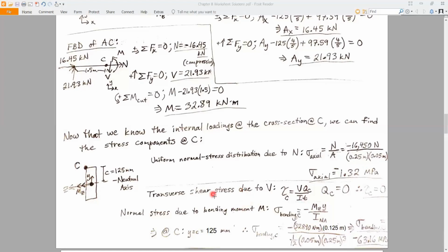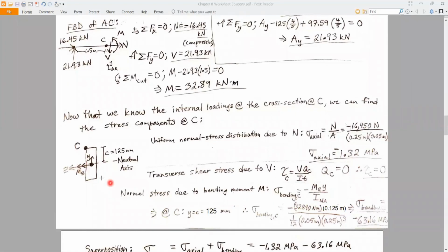All right? We know that we're not going to have any torsional shear stress either because, one, there's no torque about the x-axis, but also we don't consider torsional shear in this class about rectangular cross sections. We only look at circular ones, right? But then we have to look at our bending stress. Finally, that's our last type of stress.